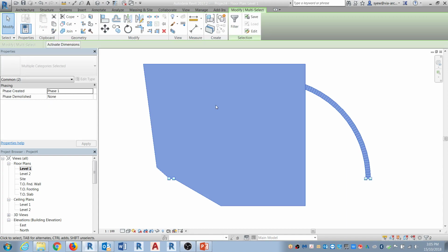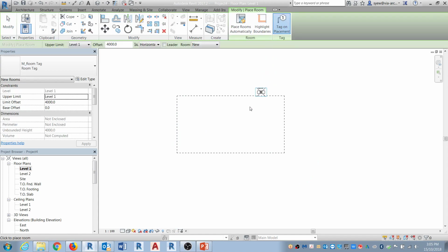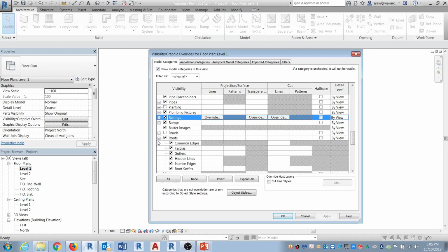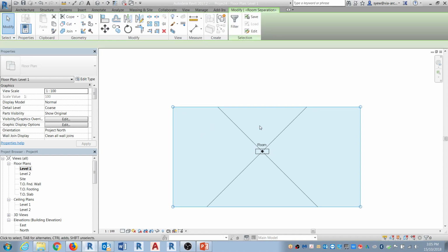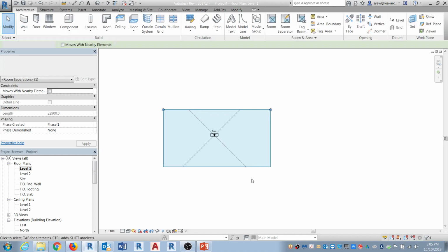Now, in the past, what we typically do is this: people would do this, right? So let's assume that you have no wall or anything. Just use room boundaries, just put in room. Just going to turn on the room. Oops, not the roof, the room. I'm just going to turn this on. Now, one of the things I don't like about using lines inside Revit is that it's very difficult to change height. Assuming that you have a split level, for instance, there's no way you can actually control this. So what I typically recommend using is